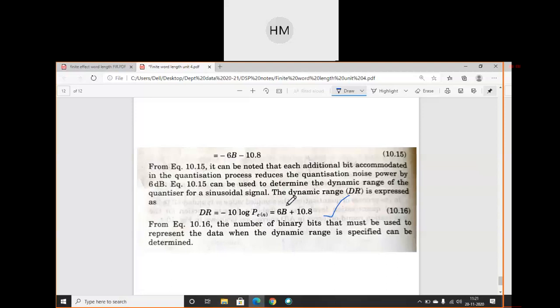So there are so many advantages of multi-rate signal processing. Advantages are: computational requirements are less, storage for filter is very less, finite arithmetic effects are less, filter order required in multi-rate applications is low, and sensitivity to filter coefficient lengths is very less. So in the next class we will discuss sampling rate conversion, how we can convert it, and how I can design a decimator and interpolator.